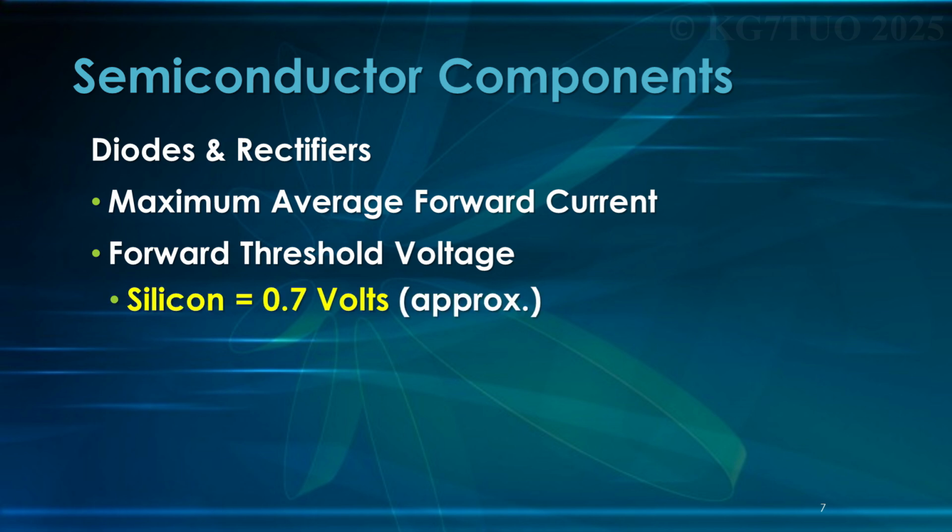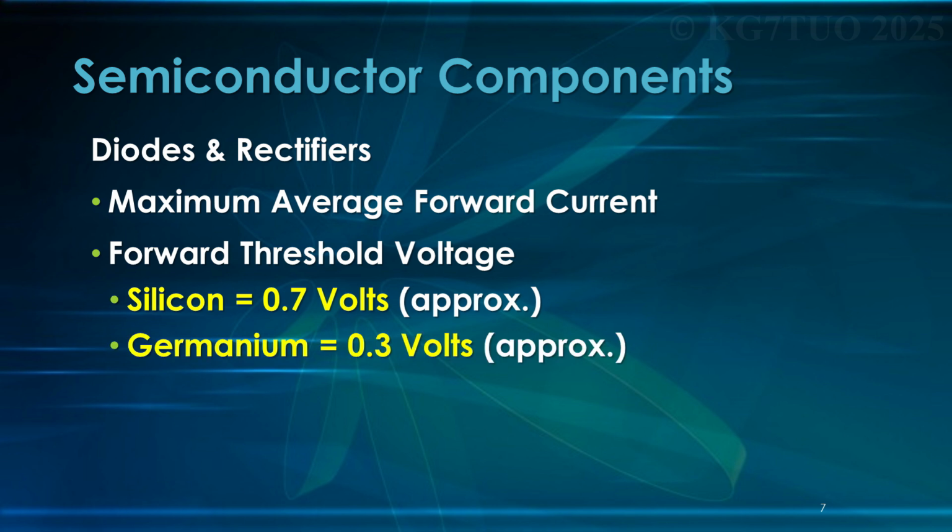Silicon, these two are on the test. Silicon 0.7, germanium 0.3. Almost assured you're going to get one of those. Yeah, that's in the general test. Wouldn't be surprised. Yeah, it is. Probably in the tech. It is important. When you're in that program on the radio and you got your voltmeter on this and you're seeing a voltage you don't understand, look at the nature of the component.